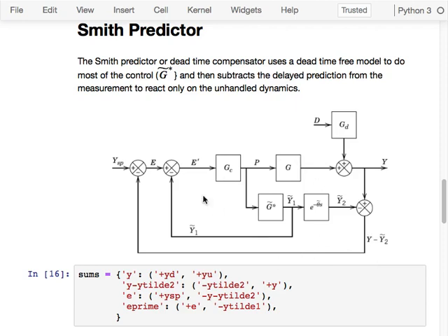Now we are doing what is normally done to simplify all the math, which is to say, well, let's just imagine the dead time is just inside of G there. Even if we attribute it to the measuring instrument, we're going to lump everything inside. You'll see it just makes the block diagram a lot easier to deal with. And so we've got this loop here, and you can say, okay, there we have the control output.